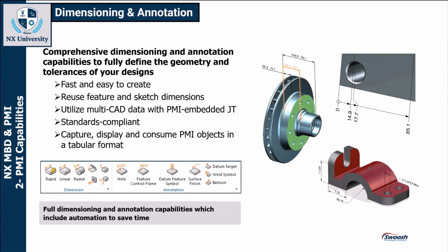If you look at the toolbar there, you'll see that those toolbars with the PMI toolset are going to be nearly identical to the toolbars you're going to see creating a drawing in the drafting application inside of the NX product. So you're going to have familiarity right there, and you're going to be able to get right into using these PMI tools and creating the PMI on the physical models inside your designs here.